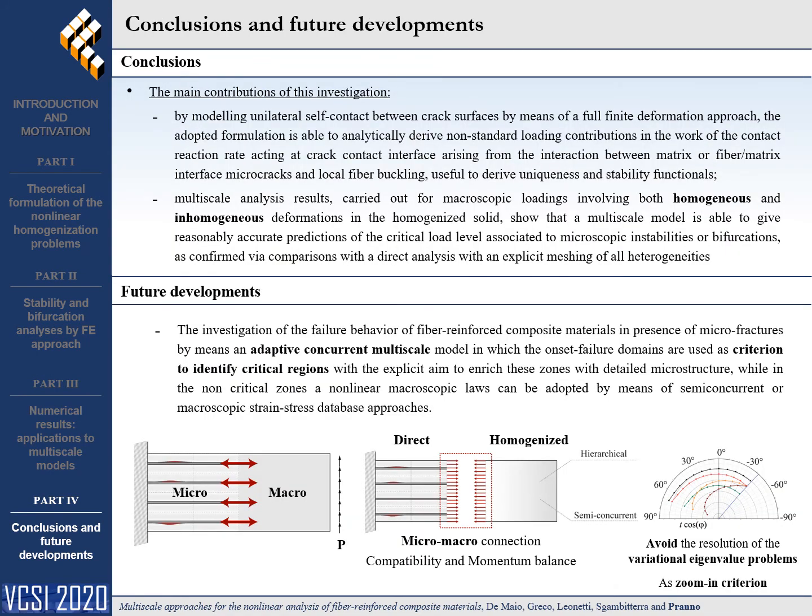In conclusion, by modeling unilateral contact between crack surfaces by means of a full finite deformation approach, the adopted formulation is able to analytically derive the non-standard loading contribution in the work of the contact reaction rate. In addition, the present formulation could be adopted in the context of multiscale approaches for predicting the failure behavior of locally periodic defected composite solids subjected to large deformation.